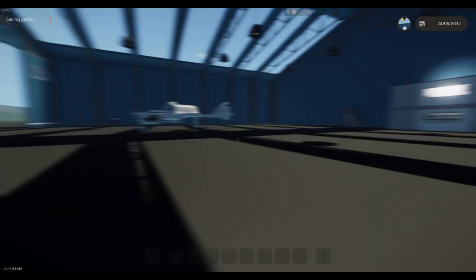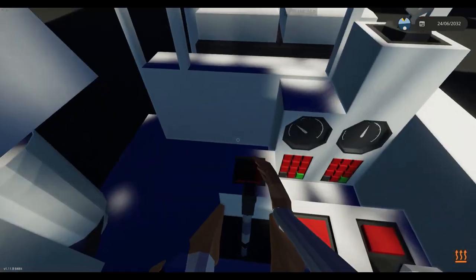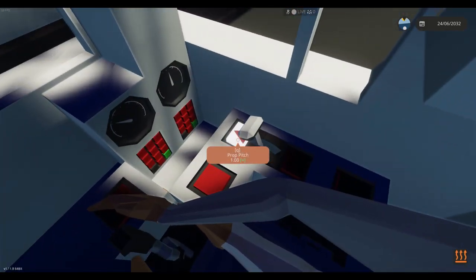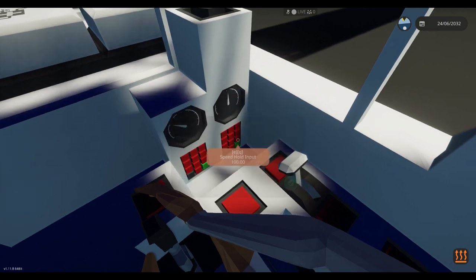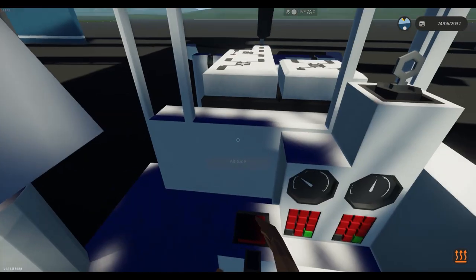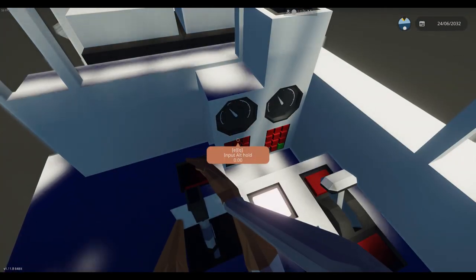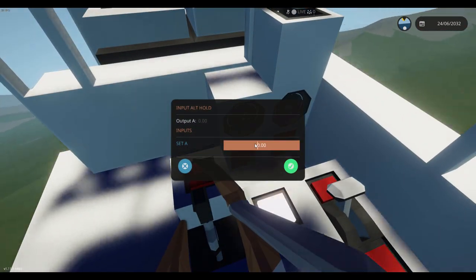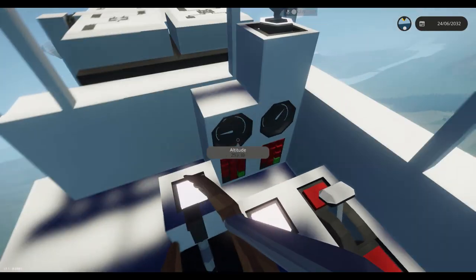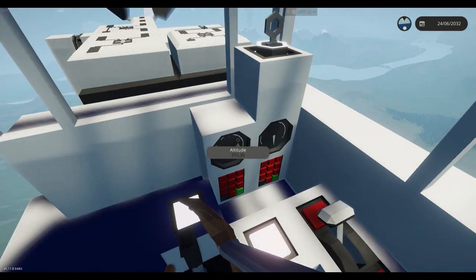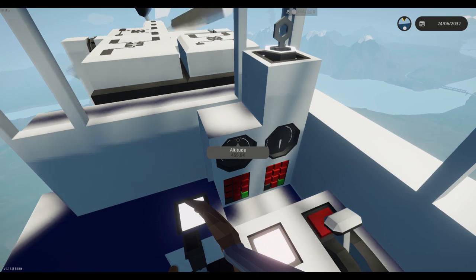We can spawn this, so we're going to test our altitude hold system again. Prop pitch. Speed, let's just change the speed just for the sake of it. Turn it on. See if we can get to 100, and then for altitude, we'll input 500 again. We'll activate it. We're at 300 right now. PID likes to control it nice and slow. So here we go, 460,